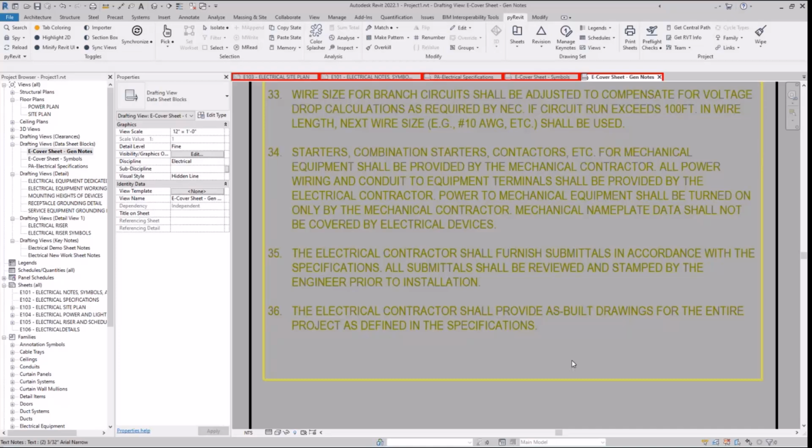But the idea is, when provide is written in these contract documents, it means the electrical contractor is to purchase, install, and do a few other things for a turnkey product of said equipment. It's basically saying, if you see provide, that means the whole nine yards, the whole gamut. You're going to go out, purchase this, submit it, get approval, install it, make sure it works. And if something blows up, you're going to have to replace it because that was totally on you. When the owner is providing stuff, occasionally I'll need to put an owner provided equipment definition in here. And that's usually a case by case basis.